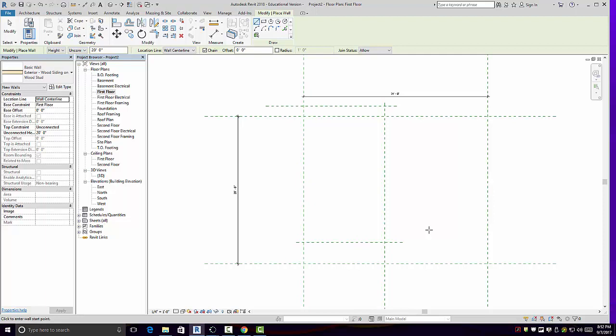Well, everybody knows what OSB is by now, right? 1 inch rigid XPS insulation at corners, which we're not going to really deal with, and R19 cellulose insulation. That's the insulation inside, and we're using 2x6s at 24 inches on center, and then 1/2 inch drywall. So we're going to modify a wall that's close to that. We can come back later and refine it.